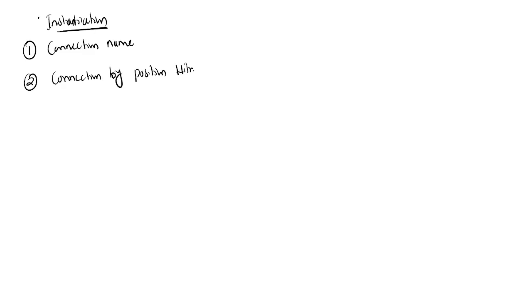So what is this instantiation? For example, this full adder you implemented by using two half adders and one OR gate. In digital, we already saw this. So what I will do is write the code for the half adder and instantiate it two times. And for the OR gate, I will write the code using gate level modeling, so that I can write the code for the full adder.